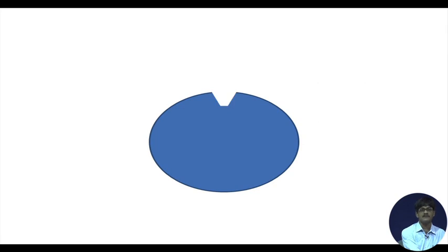After this, since the cutter can only move to and fro this way, it is brought back, and the workpiece or the blank here is rotated, so that this cut off portion moves away from the path of the tool and a new portion is brought in, and this angular rotation is exactly calculated, so that the potential tooth space, that is tooth space to be cut off, is exactly positioned in the path of the cutter. So, this is called indexing.